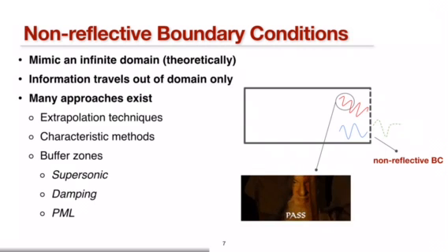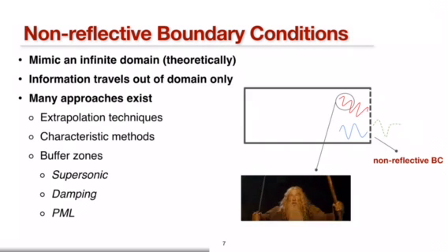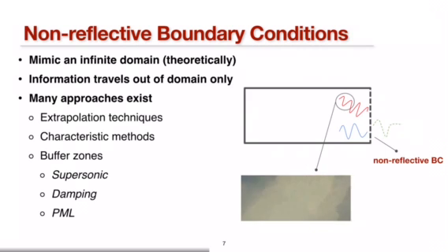In these sort of methods, the idea is simple: to extend the domain into a fictitious region in which the governing equations are modified in such a way to reduce or eliminate any reflections back into the physical domain. Some progressively increase the flow speed into a supersonic regime, while others apply damping terms in that region, be it bluntly or carefully, as is the case with the PML.